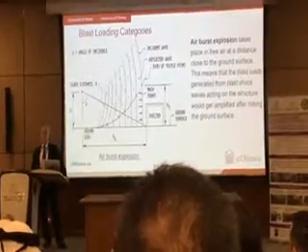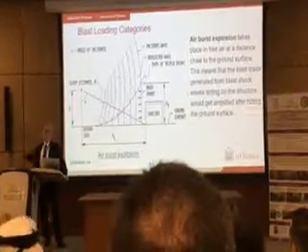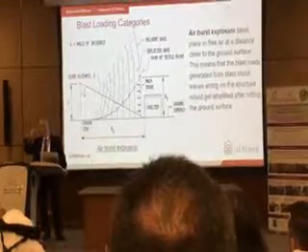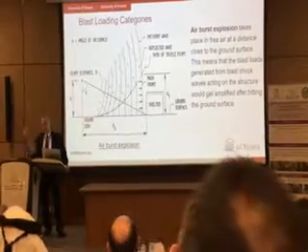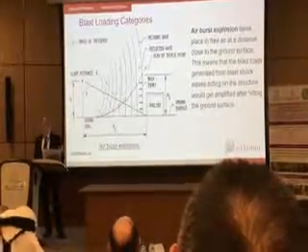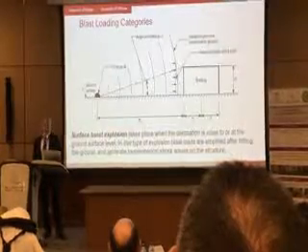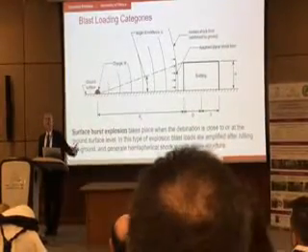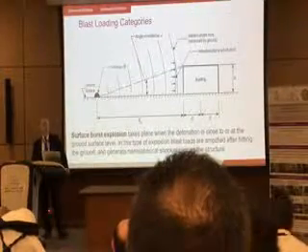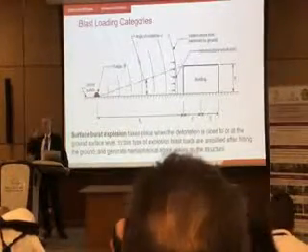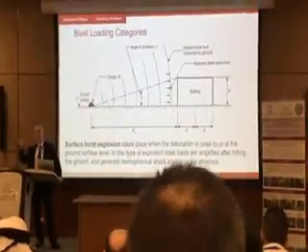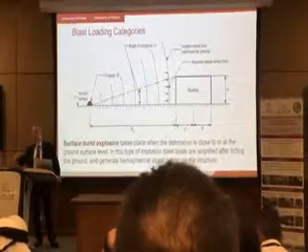But if you have an air burst explosion which is slightly above the ground, it causes, this time, semi-spherical waves, and then the magnitude of that is different. Now, if you put it right on the ground, as is usually the case when we talk about car bombs and truck bombs, then the shock wave reflects from the ground and it increases.